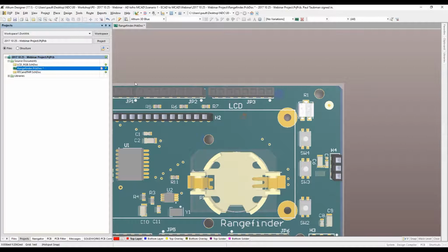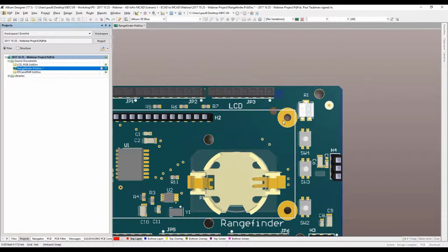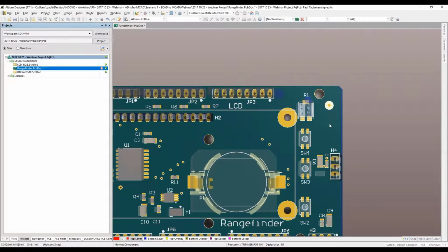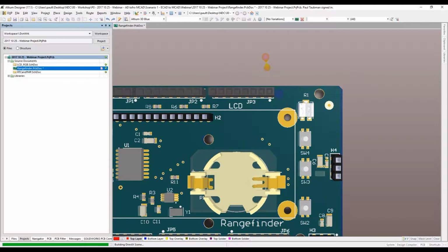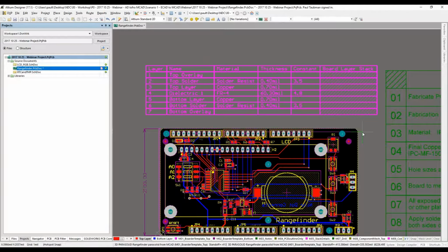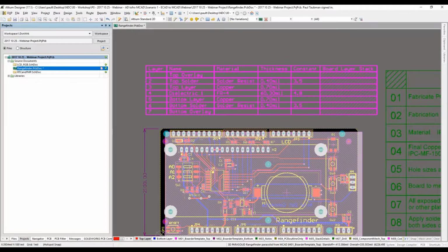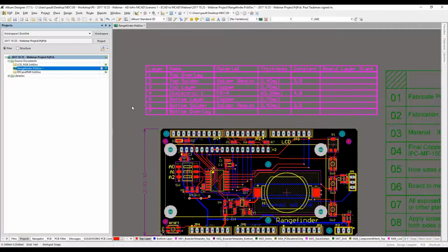So what we're going to do over here is introduce you to that. First and foremost, I'm going to paste, go to the 2D button over here, and just take that parasolid and delete it. Now, for us to use the SolidWorks Connector, we have to set up what's called a managed project, and that's something we did beforehand. Setting up a managed project is not that difficult. As a matter of fact, it's the same way you'd set up any type of project.